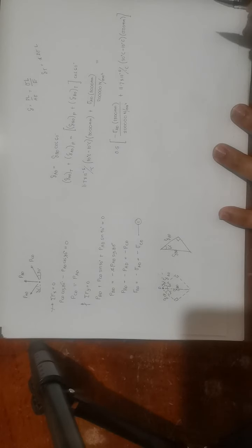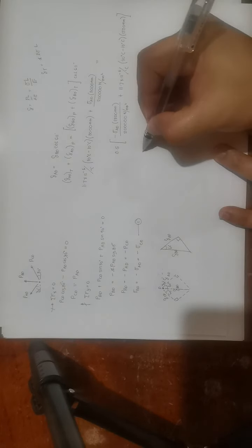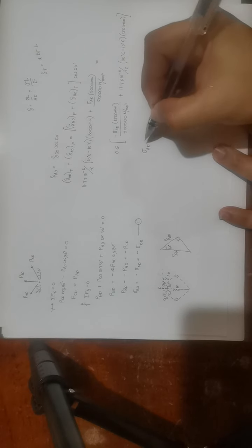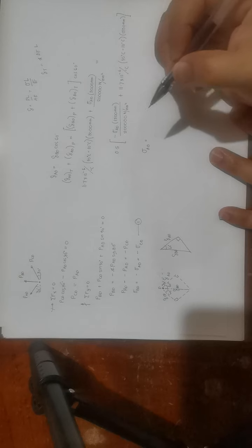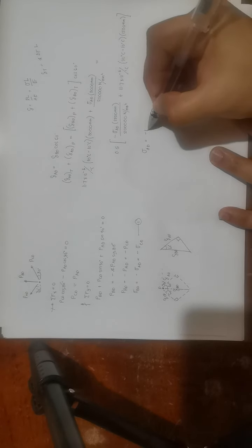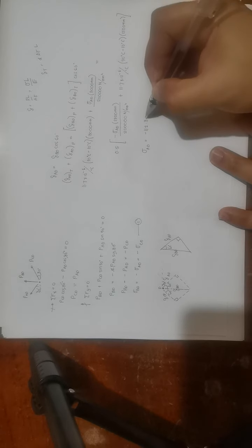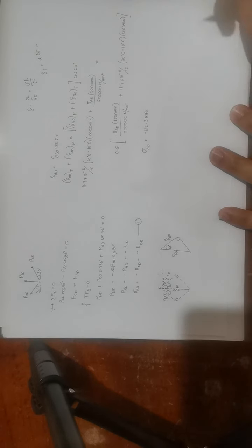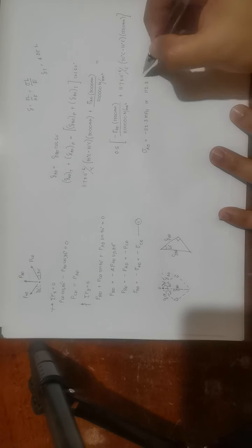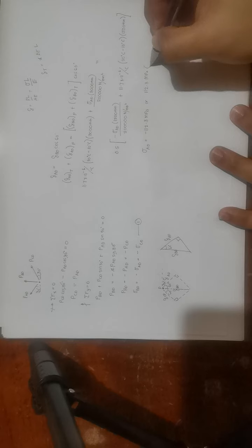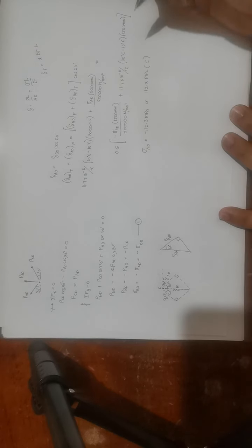So kapag ikakalculate natin yan, simplifying further, we can get a value of the stress in member AD, negative 112.3 megapascal, or that is 112.3 megapascal that is in compression.